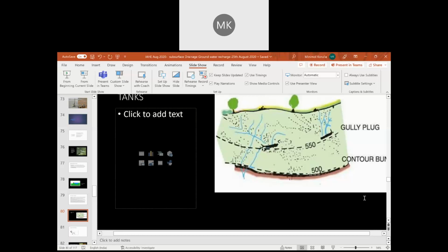So the first upper right side image, where we are introducing some drain pipes in the hill slope, okay. And the hill slope, as I mentioned, the seepage lines and the entire geology of the area should be known to decide where we are going to insert the drainage pipes, okay.